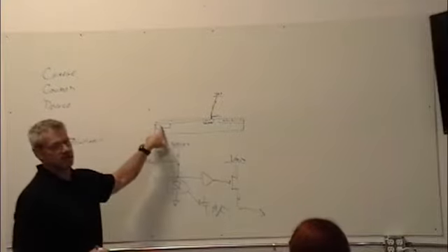you've got your CCD here, and these gates are polysilicon, which you grow on top of the silicon dioxide. It preferentially passes red. So your red CCD, if you had a red, green, blue, always gave you a better signal than the rest of them did. And so everything tended towards red. And then they figured that out and did some calibration to knock that signal down.